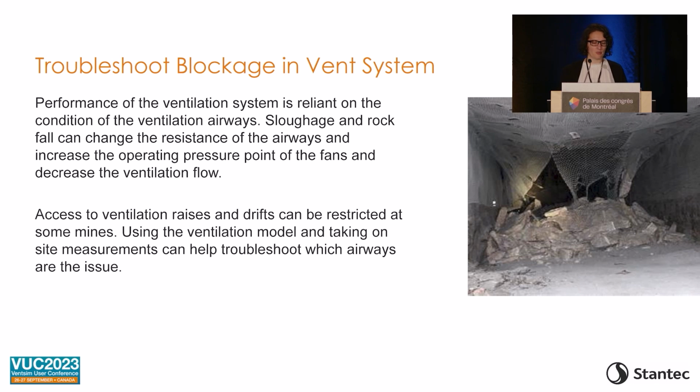And then what we did, we just worked backwards to try and see where the resistance was higher than it should have been to identify where the blockage was, and then they could do more inspections in the area that was an issue. What ended up happening in this instance is they couldn't go and clear the blockage, so they had to drive another race. But using Ventsim is a good tool to identify where it's not matching up, as long as it's calibrated, so that you can address the issue.